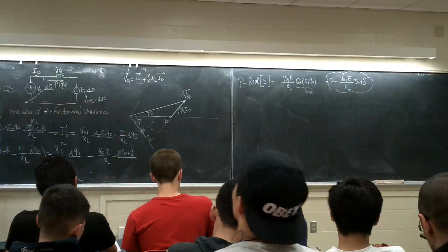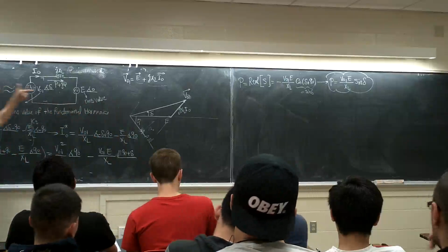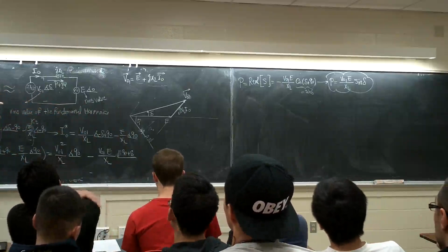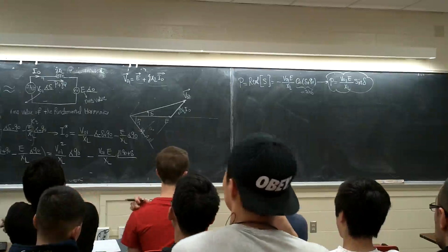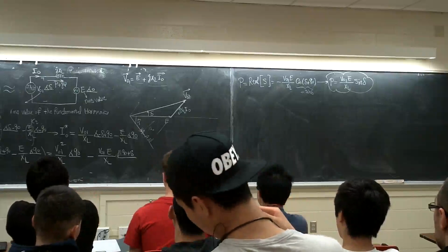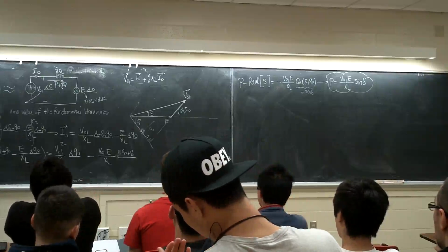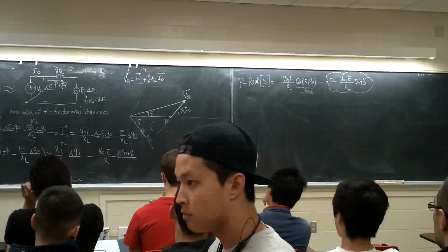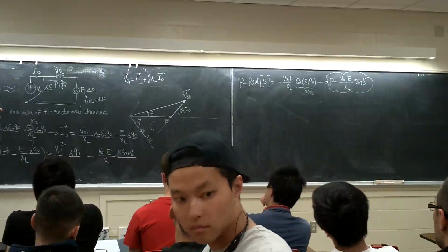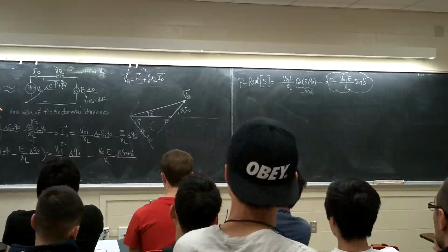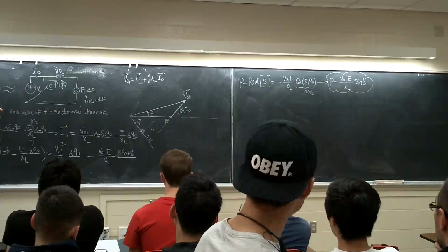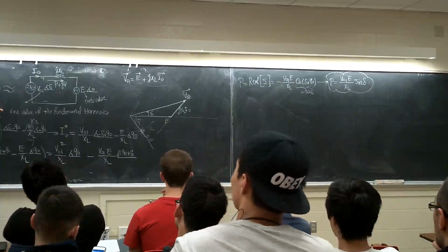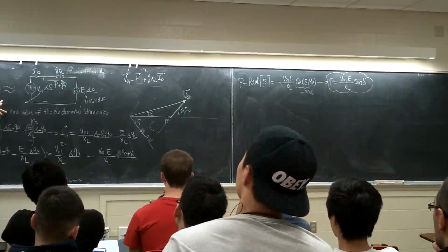So this is a very simple equation, the active power injected by this inverter. It depends on what? Think about it. When you have an inverter connected to the grid that you can control, you are going to simulate all these things later. I want you to write about the physical meaning. I don't want you to just write the equation and simulation; I want you to explain what you are doing, to understand. Look at it here. Can I change E? Why not? That's the grid voltage, and you cannot change the grid voltage. The grid is like an infinite source, a very stiff source. This one is not under my control.